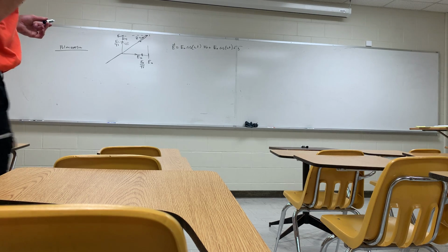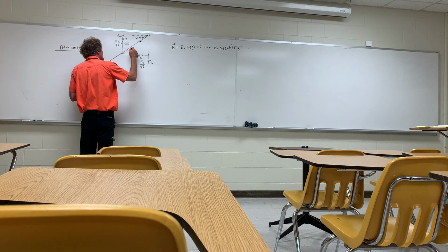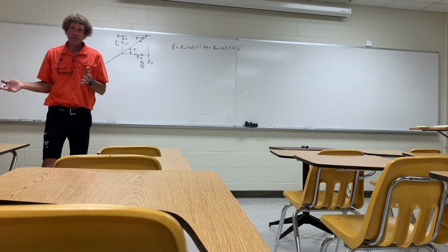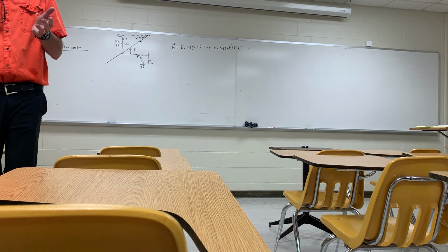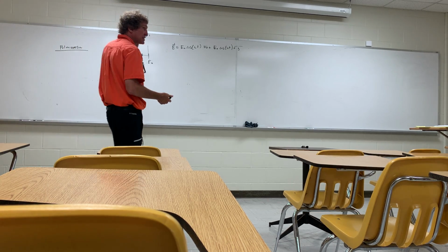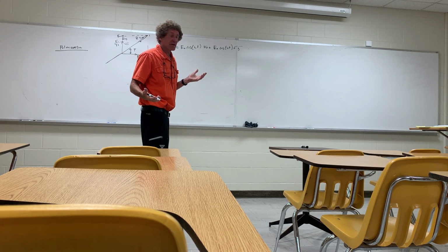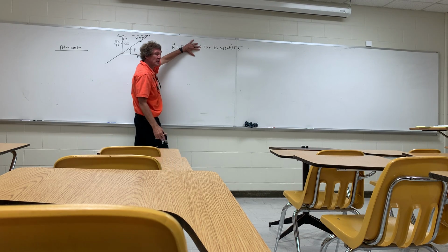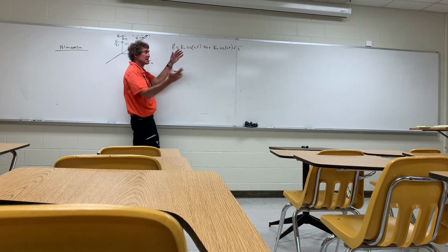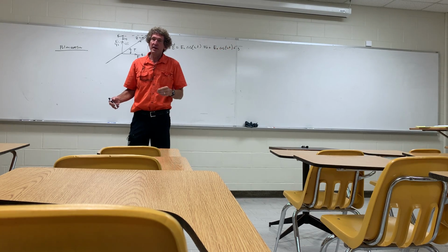That's linear polarization. In Wentworth's book, he'll talk about, he wants to know the tilt angle here. And it doesn't matter where it's from, he'll call this the tilt angle. I don't care about that, and neither does anybody else. You can see it's 45 degrees just by plotting a few points, right? So this is simple linear polarization with a tilt angle of 45 degrees. If I wanted linear polarization with a tilt angle at 90, I just get rid of the AX component. Make E naught there 0. So I only have a Y component. If I only want it in the X direction, or I want the tilt angle to be 0, I get rid of the EY component. Y'all following that?